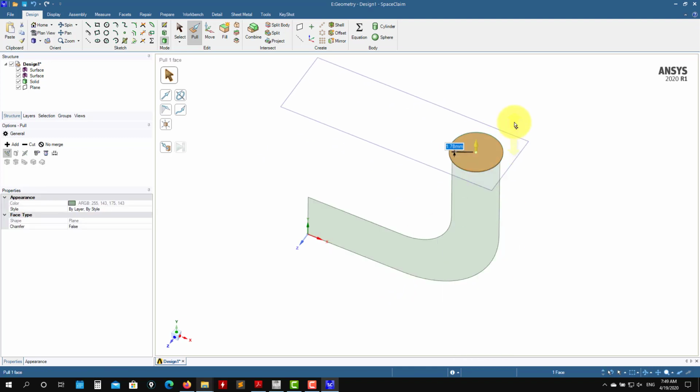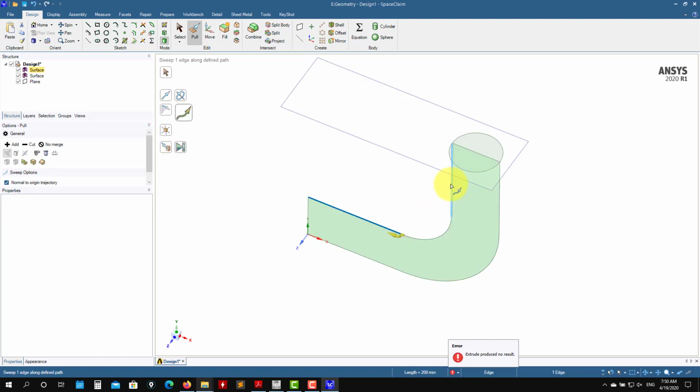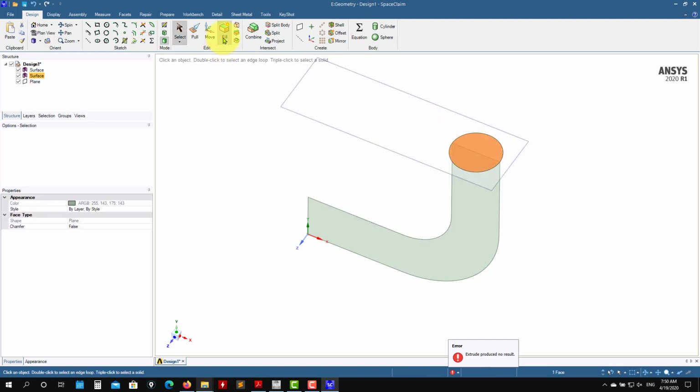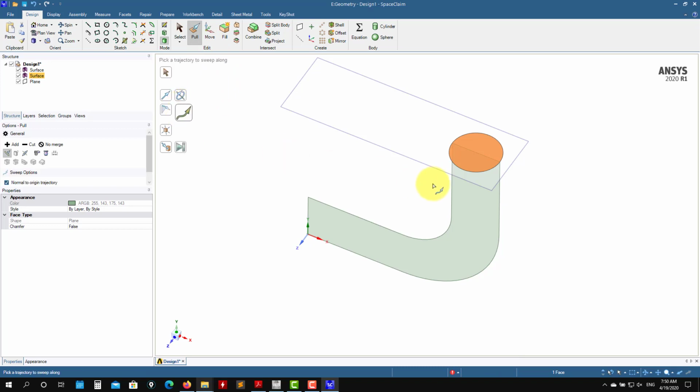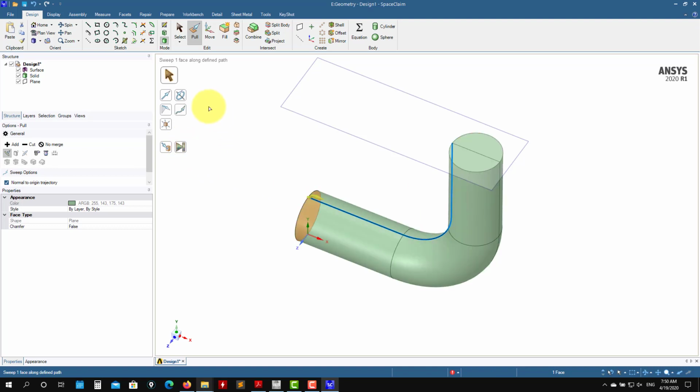So again, you can push, pull, but we want to use a sweep here. The sweep is the universal one. It works like this. Select the face, and then here you have the path. Sweep, and then you select the path. This, and this. Put it there. Oh, okay, it's control. Select the path. Control, multiple selections. Pull. Okay, you selected the face, and then 1, 2, and 3. See that it is blue, and voila, you have it there.